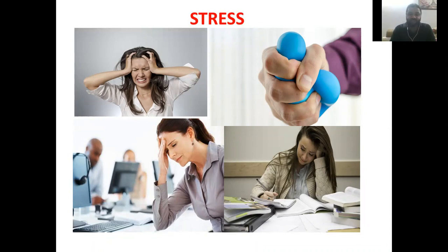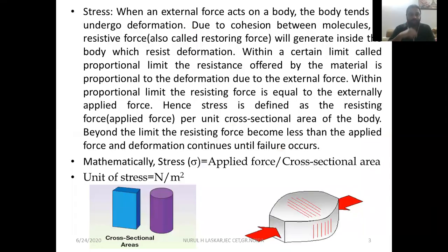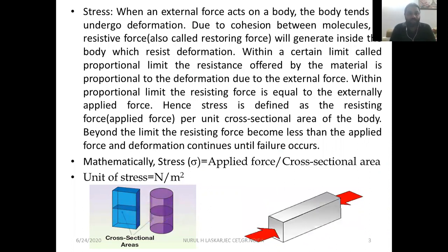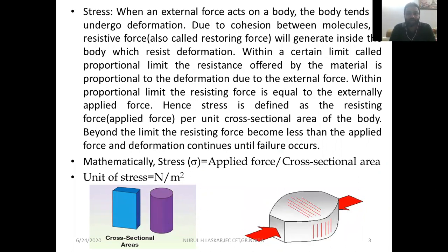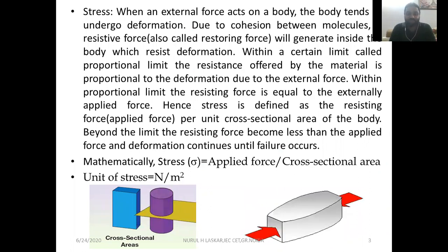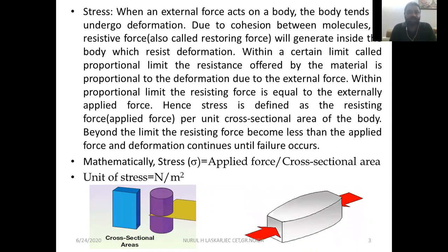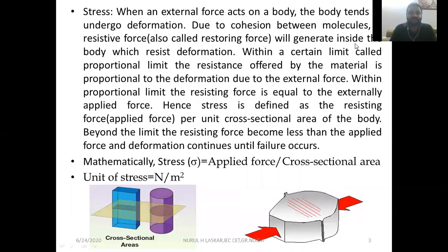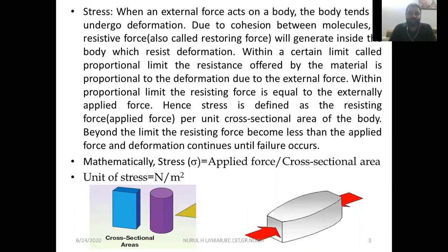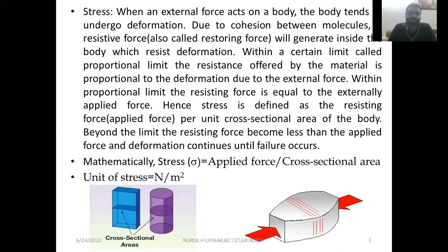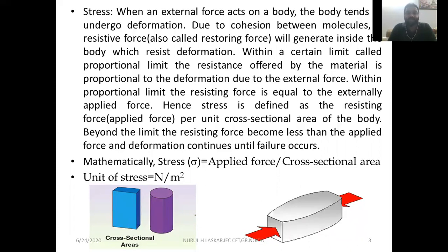So again, the next is the definition of stress. Now, what is stress basically? Or what is the stress in a solid body? When an external force acts on a body, the body tends to undergo deformation. But due to the cohesion between molecules present in the body, a resistive force, also called a restoring force, will generate inside the body, which acts against the deformation. And that is in nature also. If any force acts on a body, then normally the body will first try to resist that force. That is, the body will always try to remain in equilibrium.